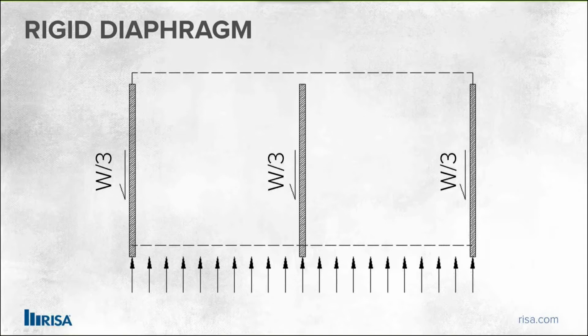Now you'll also notice my deflected shape of that. It's sort of a rigid, idealistic idea of the fact that this is completely rigid. Internally, the thought is that you're basically tying all of this with rigid elements under the hood of the structural model, where you're applying that load, and it's going to be using those rigid links to tie every single element together. And as you apply the load, it gets distributed into that model.